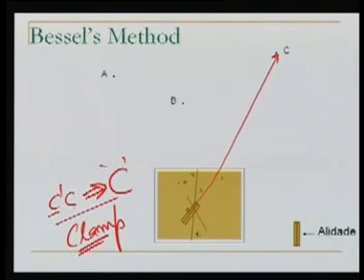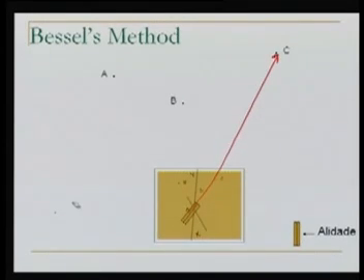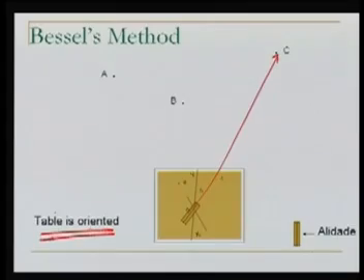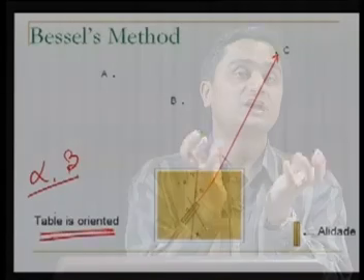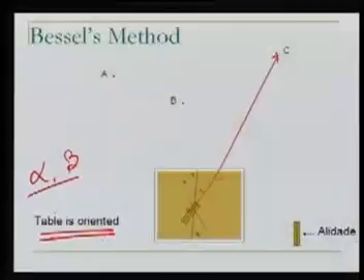If we have performed all these steps, what we will find, what we will notice? At this stage, the table is oriented. So this is really interesting, how by following these steps the table gets oriented. If you get into this method, you will realize that basically again the same alpha and beta angle, we are playing with those angles. We are generating those angles here also. And somehow, as in the tracing paper method, we are doing something similar by following these steps, but it's not trial and error. We have our table oriented here.